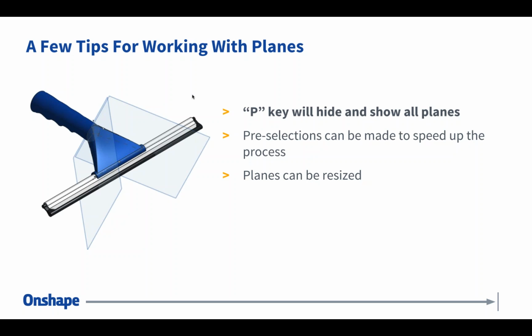Now, another frequently asked question is, can I resize planes? What is the length of a plane? Does the plane size in the graphics matter? Yes, planes can be resized, and I'll show you that in just a moment. But it's important to remember that planes are essentially infinite length.